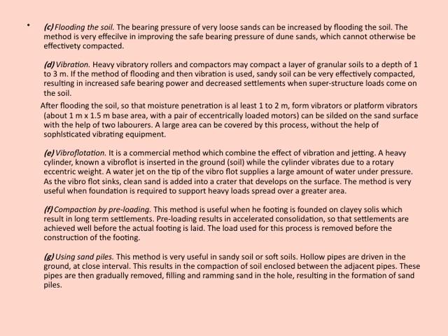Moving on to vibroflotation, this is a more advanced, commercial method that combines vibration with jetting. It uses a heavy cylinder called a vibroflot, which vibrates via rotary eccentric weights. Water under pressure is supplied through a jet at the tip of the vibroflot, which helps it sink into the ground. As it sinks, clean sand is added into the crater created on the surface. This method is particularly useful when supporting heavy loads over a wide area, as it significantly improves the soil's capacity.